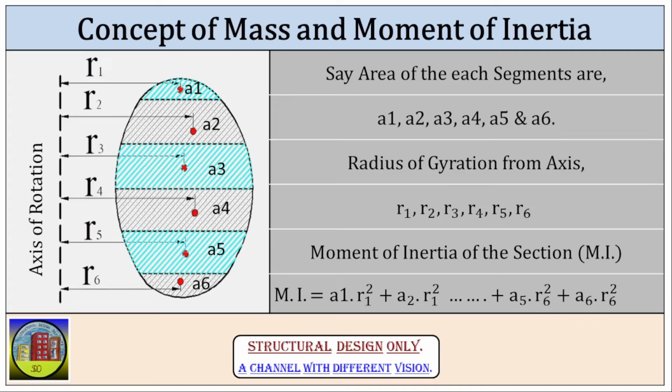Traditionally, moment of inertia is calculated using the total mass of an object and its radius of gyration. But what if the object has a uniform density and thickness throughout? In that case, for thin plates or sheets, we can actually use the area of the plate instead of the entire mass for moment of inertia calculations.